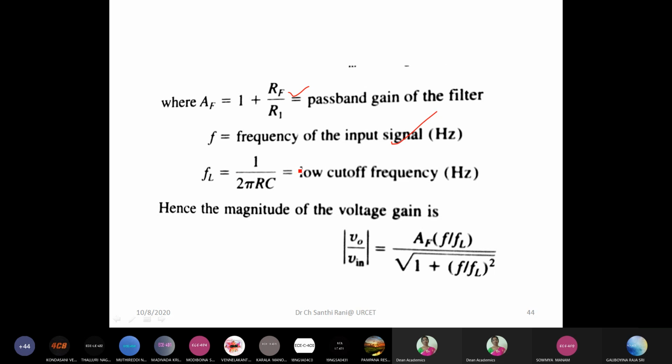That is why we say low cutoff frequency for the high pass filter. For the low pass filter, we say high cutoff frequency, because all low frequencies are allowed to pass. As we increase frequency, at a certain high frequency it starts providing attenuation. This is a low pass filter, so we call this frequency the high cutoff frequency. Whereas the high pass filter...